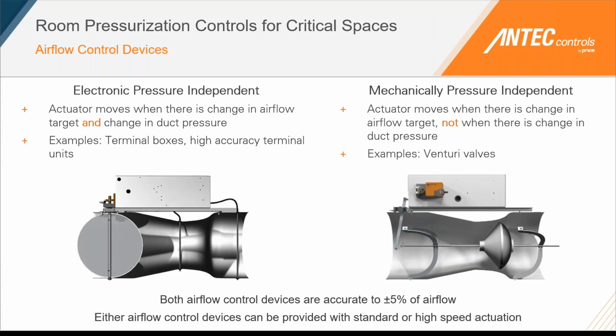So this can include terminal units or high accuracy terminal units. For mechanically pressure independent valves, instead, we have the actuator move when there's a change in the airflow target, not when there's a change in the duct pressure. So classically, this is going to be your venturi valve.